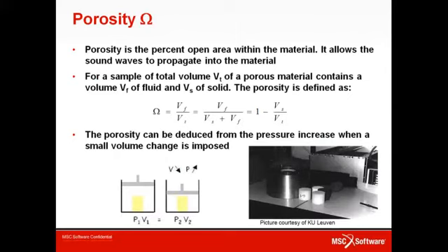The porosity is the fraction of open area within the porous material, and as such, it is defined as the ratio of the fluid volume by the total volume of the foam. It can be accurately measured by placing a small material sample in a small cavity into a thick metal cylinder with a large thermal inertia. The porosity is deduced by monitoring the pressure in the cavity before and after the change of volume, assuming an isothermal compression process and neglecting the compression of the solid.